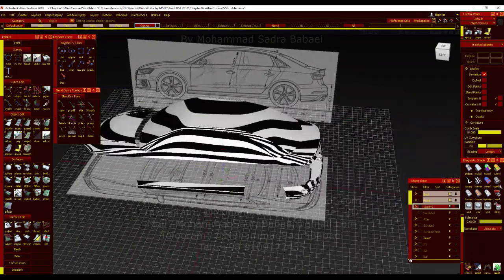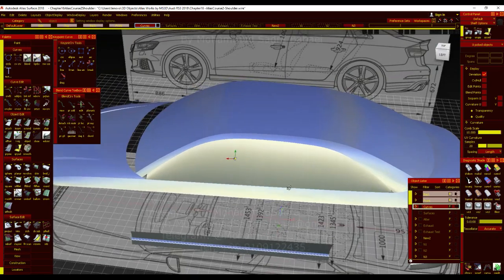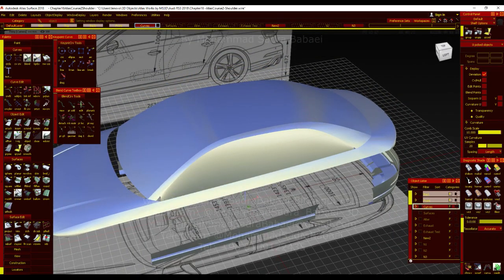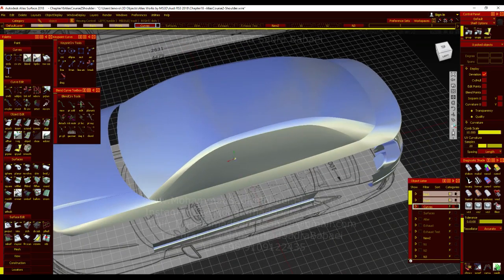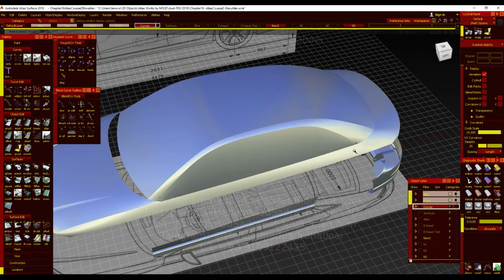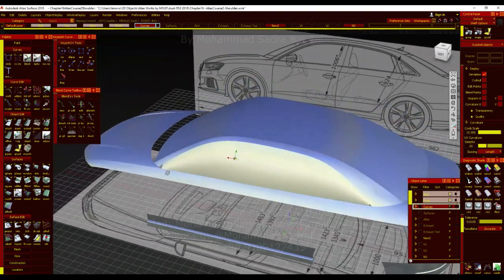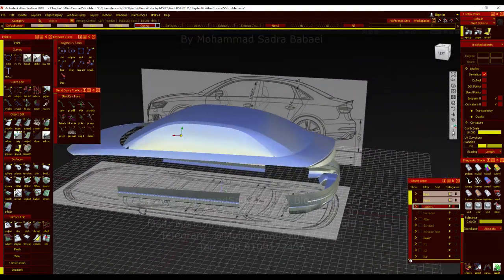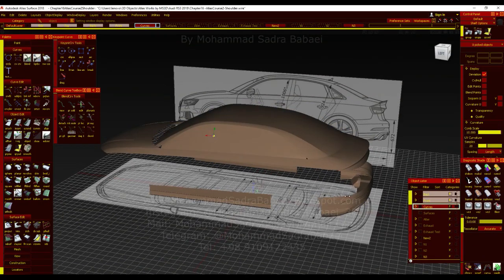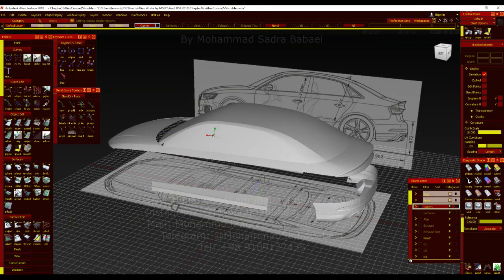So work on this area, work on your models and your concepts for your remodels, and my suggestion is to create the glass first and then create the shoulder, the roof and the pillar. This is the correct way in automotive A-class modeling. So take care of that, because it is very important, and that's the difference between you and other modelers.